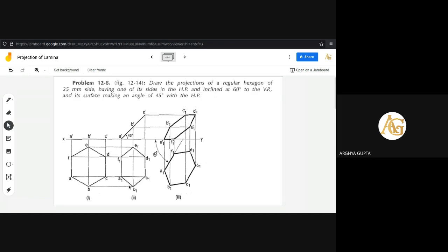If you extend A1 beyond this, you have to extend A1 beyond this. So mark that distance, take the distance and mark it here also, and through that point to this point, draw a perpendicular line. So let us say this point is here. So through this point you need to draw a perpendicular line and take the measurement from this point to the B1, same as the E1 has been found, the same way B1 will have to be found. So take the measurement, so B1 will be found. Now we have found all the A1 up to E1. Now join with that thick line, so you will obtain A1 up to F1.